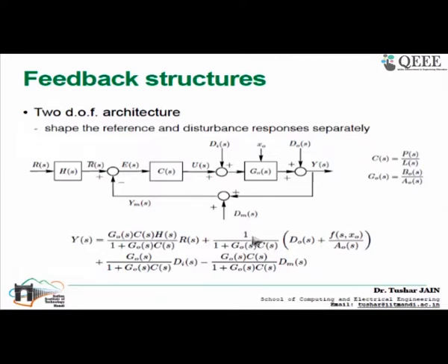So the approach I took was to design this controller C of S such that it shapes the response with respect to the disturbance. Then I designed my H of S such that it gives me the desired response with respect to R of S. Here I am designing two transfer functions, C of S and H of S, so that I can shape the reference and disturbance responses separately.